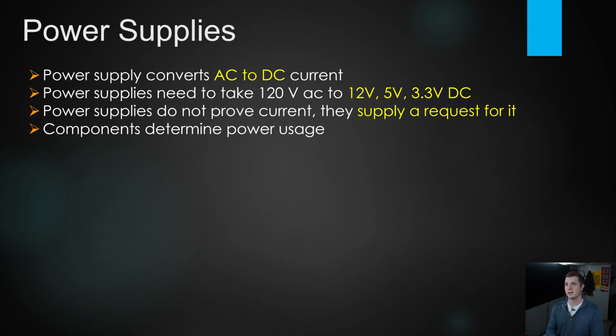All right, power supplies. As far as you guys need to know, it takes AC to DC. It takes that AC current to DC, but it also provides 12 volt, 5 volt, 3.3 volt DC. So this is basically what a power supply does. Here's a few rules of thumb. The heavier the power supply is, that's not filled with rocks or something, which has happened in the past, generally the better the components, okay?